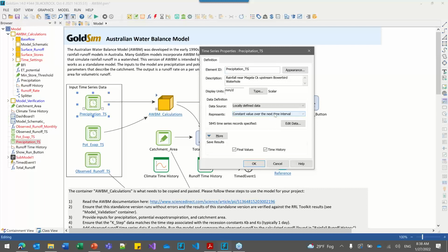to understand what happens if you have an unscheduled time step. Let's say in your main model, for whatever reason, maybe you're simulating an earthquake that happens randomly, or you're simulating some other tailings facility or a reservoir or something that causes an unscheduled event to occur in which all your elements need to update again at a time other than your scheduled daily update. So if that occurs, and this is set to instantaneous interpolated, well, what that means is your precipitation value will now be different than what it was at the beginning of the scheduled time step. And that can have an impact that's unexpected and different from what you might see in another tool like the